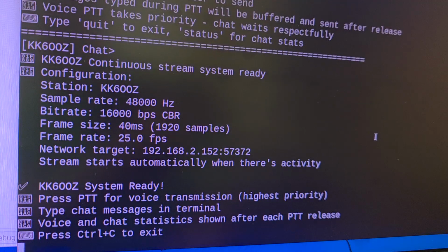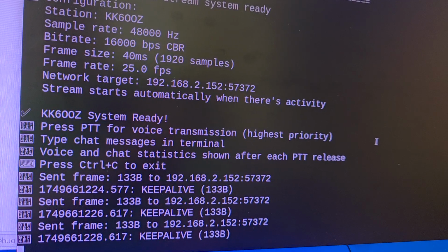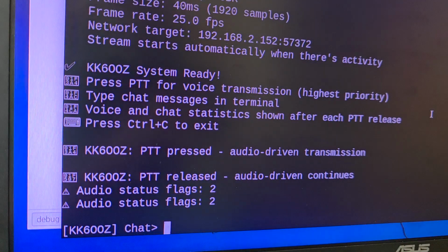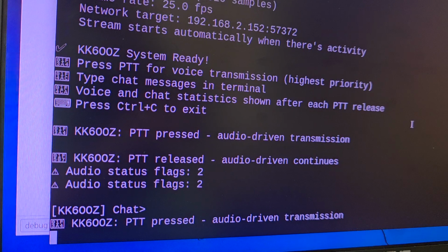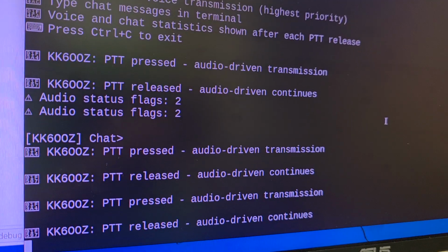What we're doing instead is encapsulating the frames that the host would be building for the modem in UDP and sending them over my LAN to another computer, which happens to be this one that I'm talking to you on, displaying as much as we can of the data and using Wireshark to capture the rest of it, and working toward a design that would allow you to build an Opulent Voice radio that has all these features, whether in one integrated thing or in two parts, one for the head end and one for the back end modem.